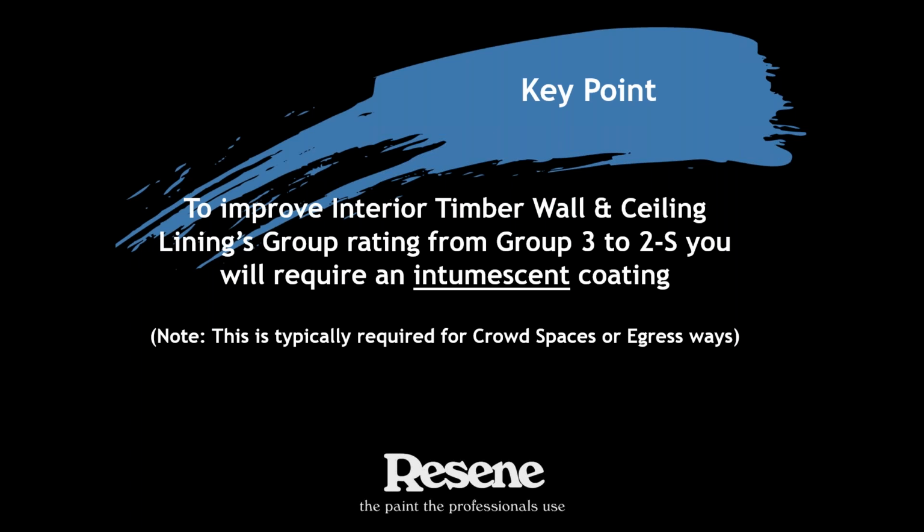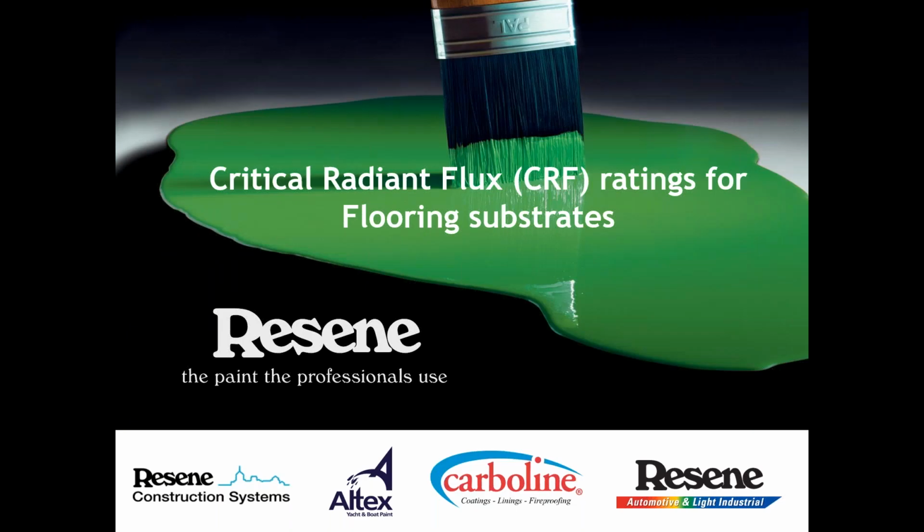So we'll go into intumescence in another webinar in more detail, and we're not covering them off today, but it's really important to understand that you will require an intumescent coating. Almost always, they are a specialist applicator or approved applicator type of product. So you can get caught out sometimes if it's rolled into your specification and just a standard painting contractor is dealing with it. You're more than likely going to require a specialist applicator to put an intumescent coating on.